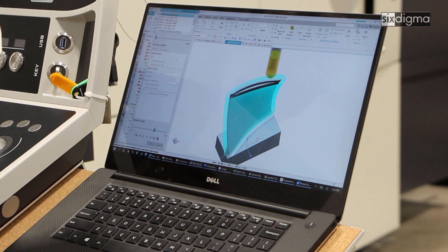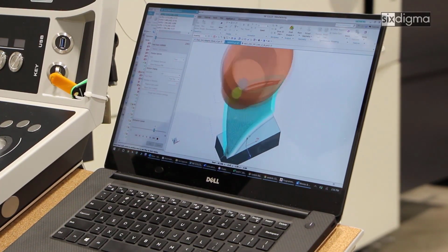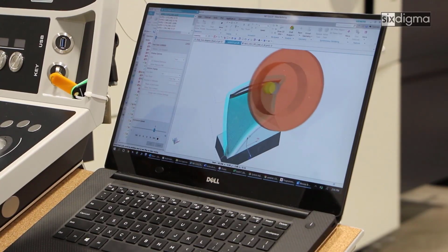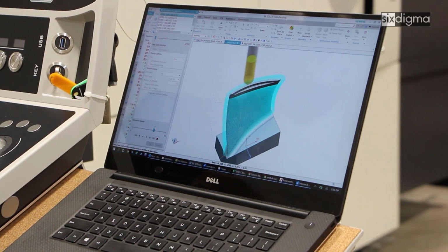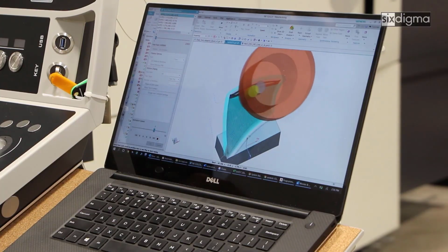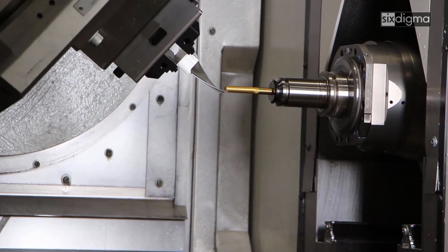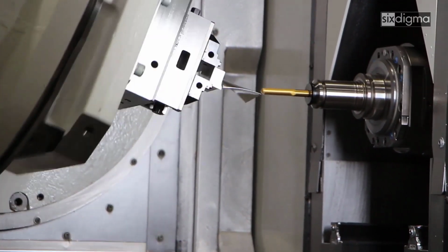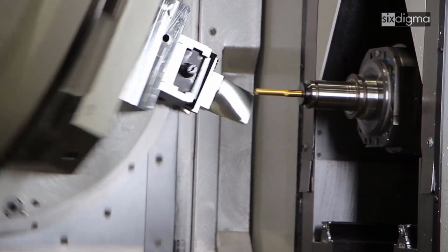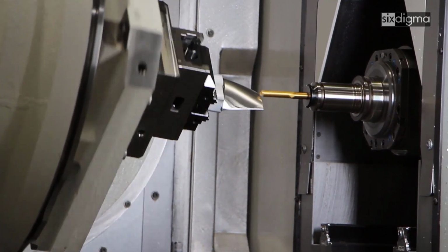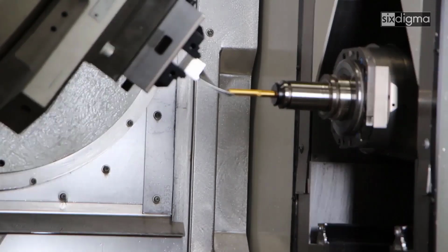Even if the rotary axes of the machine can respond quickly, the linear axes have to catch up and be in sync. Navigating around the tight leading and trailing edges always requires a high dynamic response from various machine tool axes. Siemens path smoothing options in cycle 832 and Grob's customization of it for its machine kinematic and dynamic behavior produce excellent surface finish right out of the box.